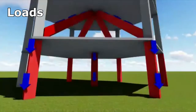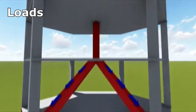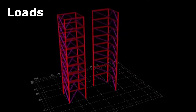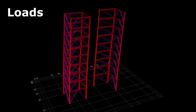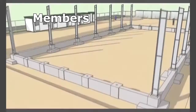Dead load is a constant weight that does not alter, as it is the building's self-weight, entities that are permanently attached and cannot be moved. Live load are non-permanent entities able to be moved in and out of the structure, such as people and furniture that is not fixed. Finally, exerted wind force on the building surfaces is measured in wind load.